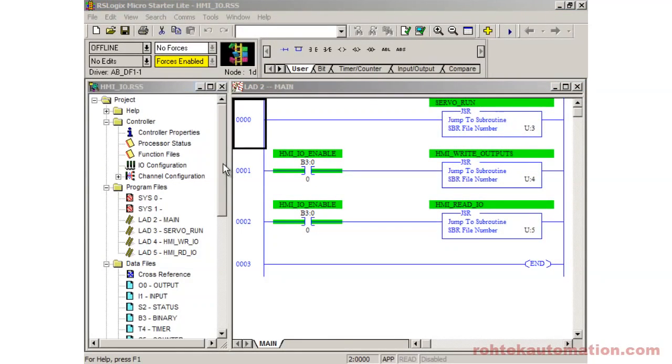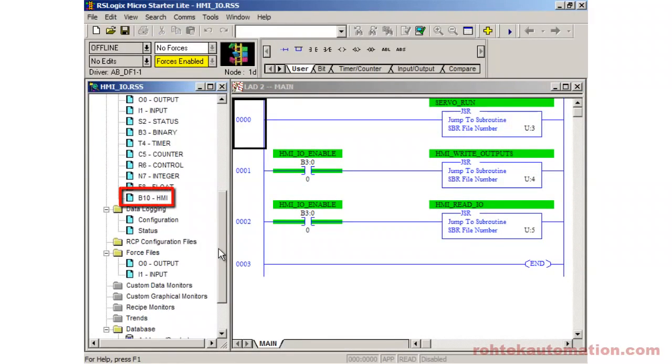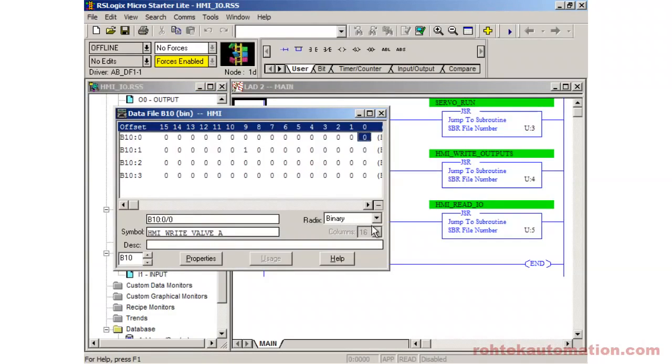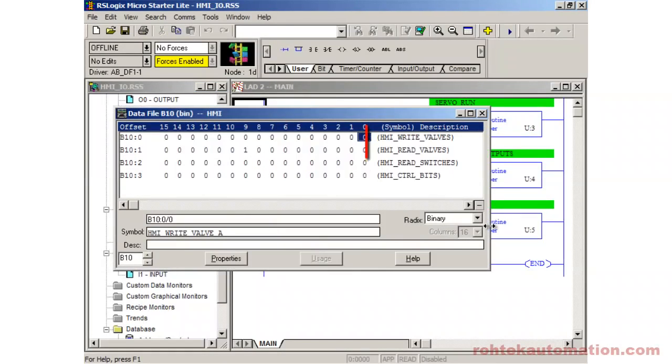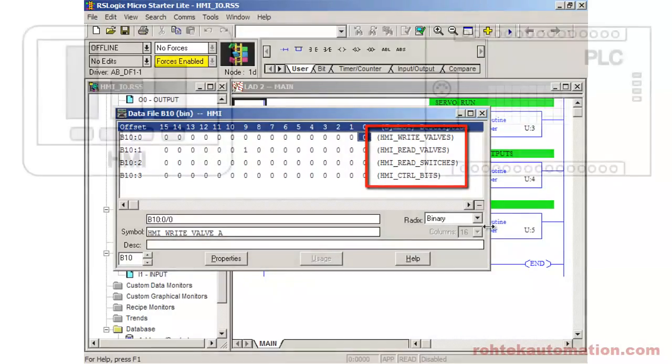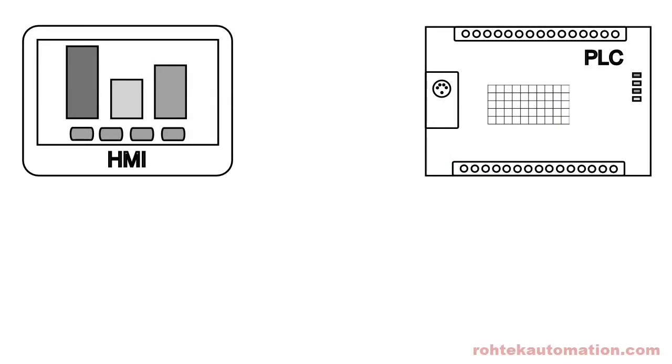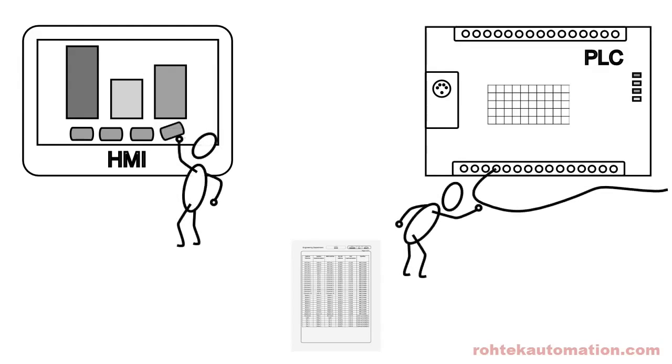The presence of the interface table in the PLC code or configuration is itself a kind of documentation, if you will, making it clear to those modifying the PLC program that there are HMI requirements to be considered. But ideally, the interface table is described in a document that is kept up to date as changes are made to the system design, HMI functionality, and the PLC implementation. This is particularly useful when the development or maintenance of the system entails more than one person working on it.